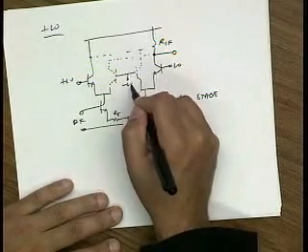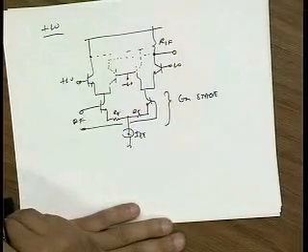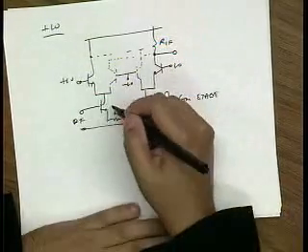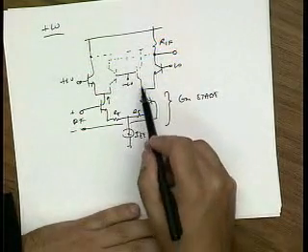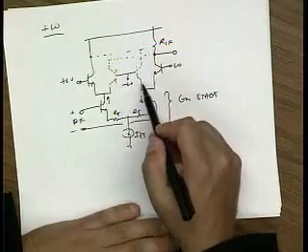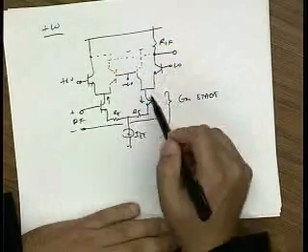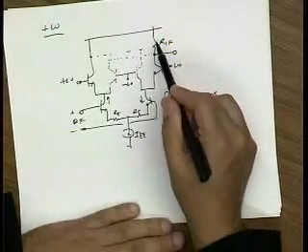And this is the minus LO. Okay? So I'm assuming extremely hard switching. And so you could see that the differential current flows to the output with a certain value of gain. In the limit that this is very hard switched, all the current goes to the output, so the gain would be, let's say in this case, +1.